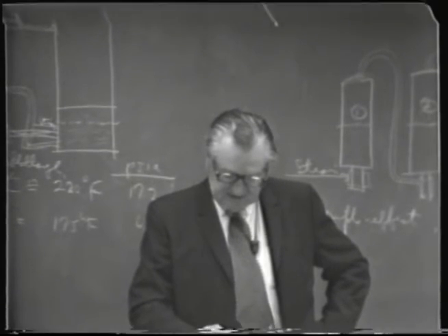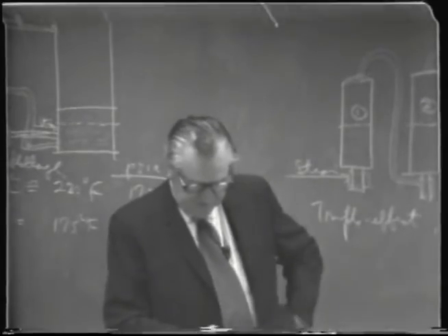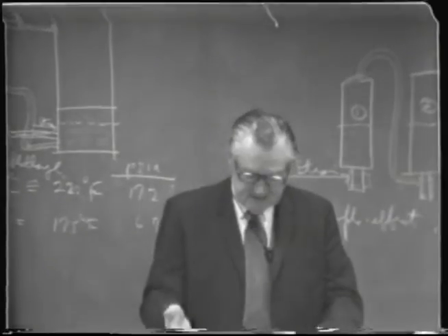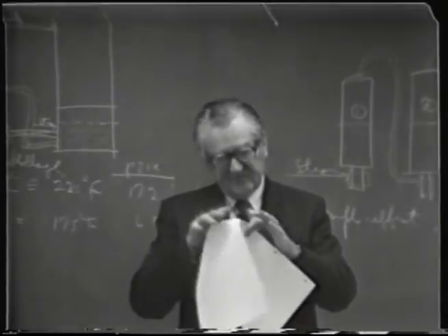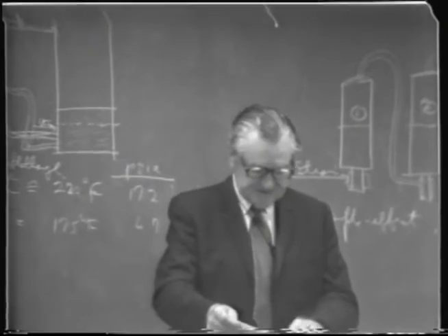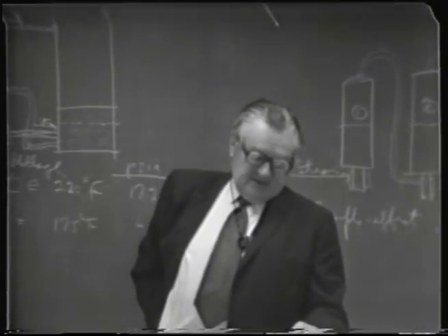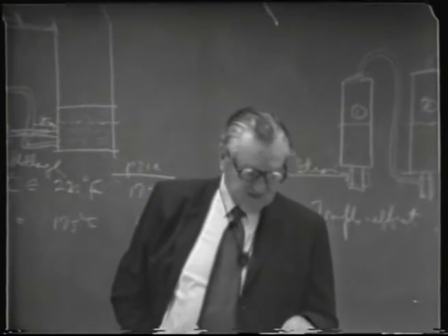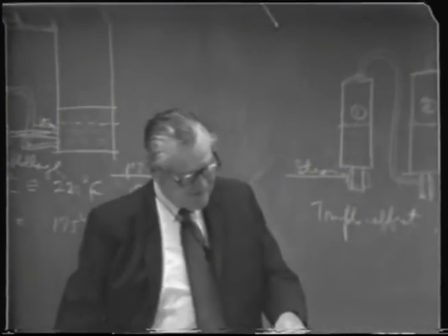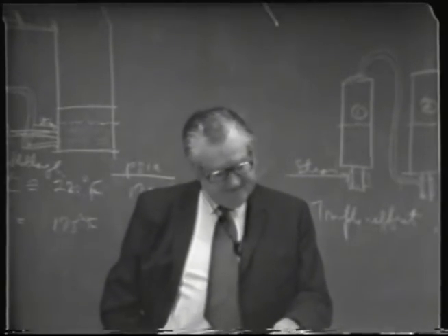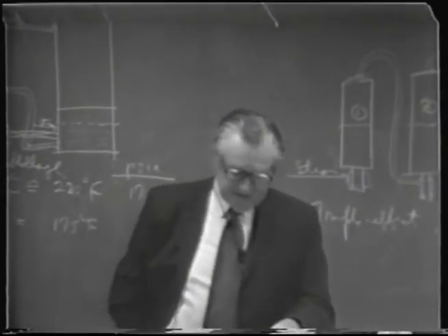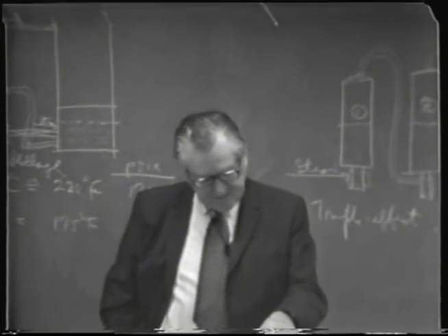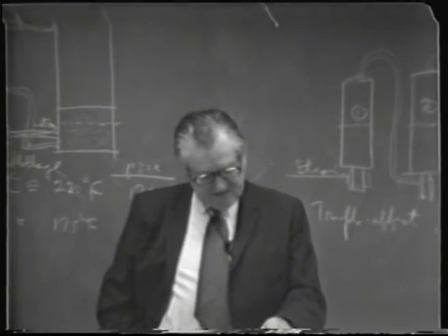The other feature is that only a portion of the overall alcohol in the feed was redistilled as heads. Whereas the next drawing we're briefly referring to is an alternative arrangement that's sometimes used, in which there's no attempt to separate heads from the primary concentrating column, but rather the product is taken over the top as a top product, then fed into what I call an aldehyde separating column, from which heads are taken off the top, and the bulk of the alcohol comes out the bottom.